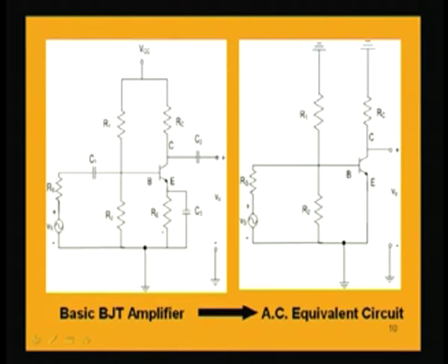It will not take the path through this resistance, because when it is offered a very easy path with no resistance at all, obviously this resistance will be bypassed. So, there is no purpose for this resistance to exist here, because this short circuiting part is there. That is why RE is removed according to step 3. Now, this is the equivalent circuit under AC.